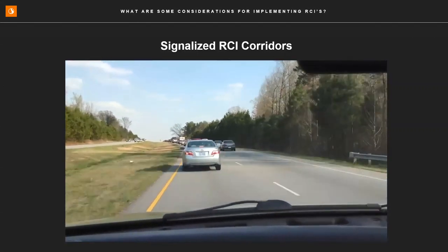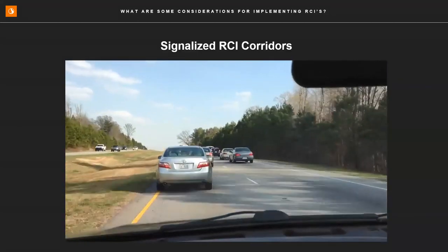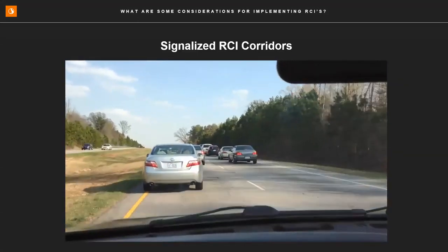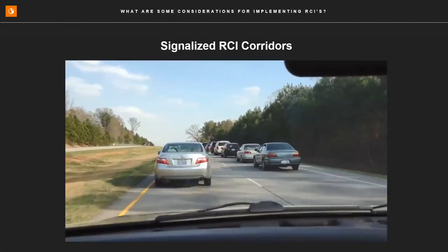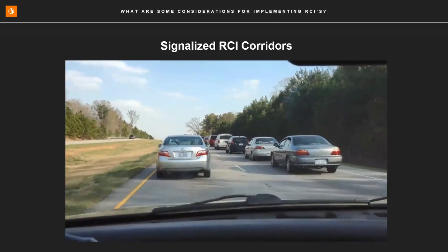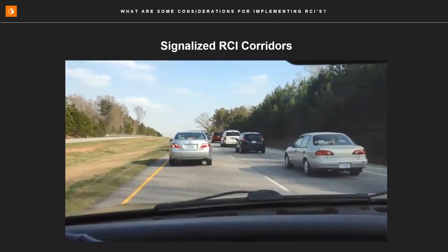Remember when I said there wasn't a single solution for all intersections? Well, this intersection that was a logjam had a large residential community and a school located along one of the side streets. With this heavy side street left turn movement, there's hesitation about redirecting that large of a volume to a U-turn. What ended up being the final decision was what was known at the time as a reverse RCI.